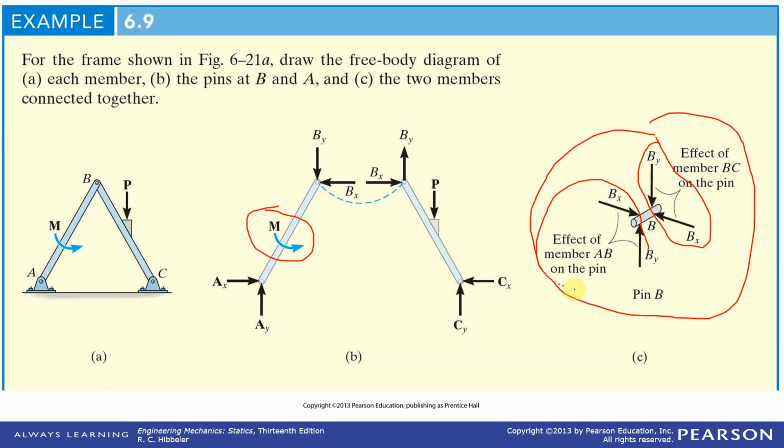These are the forces associated with the left-hand member. This is the force of the left on the right. This is the force of the right on the left. Okay? Which is why these things come in pairs. Carefully draw your free body diagram to show this. Then you can analyze a frame or machine. Moving on, next video.